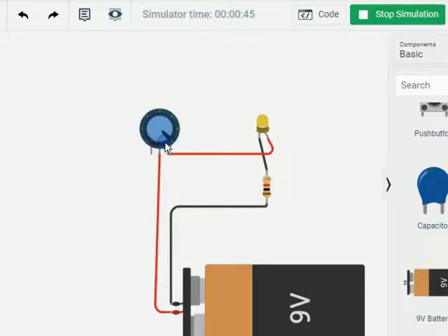All right, and let's see, I think, let's try, nope. There you go. All right, so let's do this. Oh, I see why. The reason why we did not pop this LED light is because we have a current limiting resistor right here. Because right now there's no resistance across these two pins, so with full contact, all the current coming from this pin, the output of this battery, is actually going to the LED light. But since we have this resistor, it's not allowing the bulb to blow up. And I'm going to show you guys right now what happens when we take that limiting resistor out.